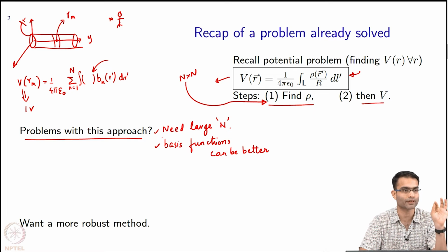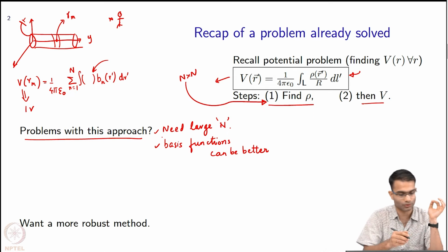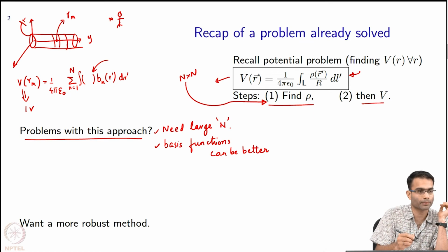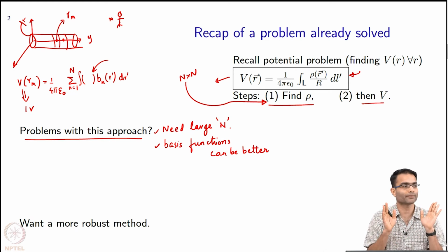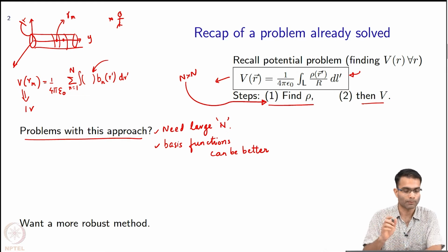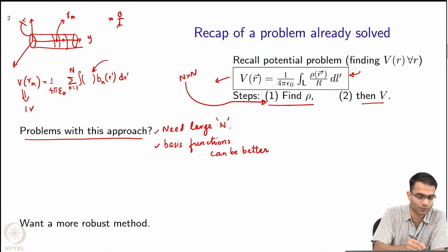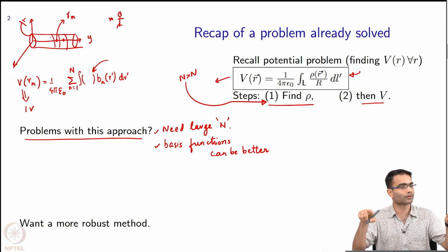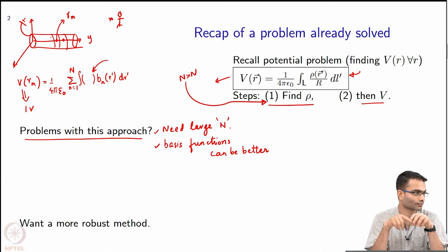We are enforcing the left hand side at Rm, then the next, so we have one segment over here, we have one more segment over here. So first equation will take this point, second equation will take this point, and so on. But we are doing nothing, we are just hoping that the solution turns out to be smooth and well behaved and all of that. But we are not doing anything to ensure that the solution is continuously 1 volt everywhere. The voltage that is given is at every point on the wire. But we are increasing n. As we increase n, we are approaching that.